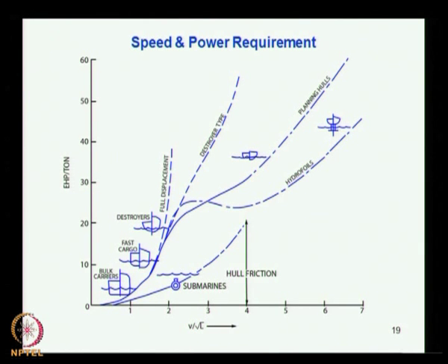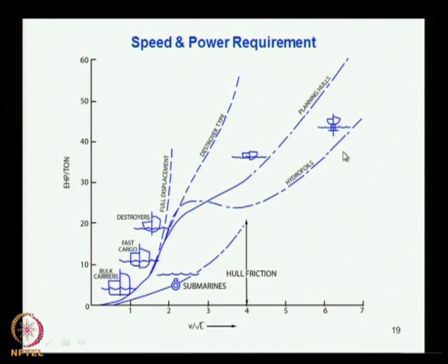There are two types of hydrofoil: the surface piercing type, and the submerged foil type. At high speed the vessel attains an operating situation which you call the foil borne condition. Only the foil is beneath the water, and the whole hull is lifted above the water, thus bringing down the resistance and enabling high speed for the same power.